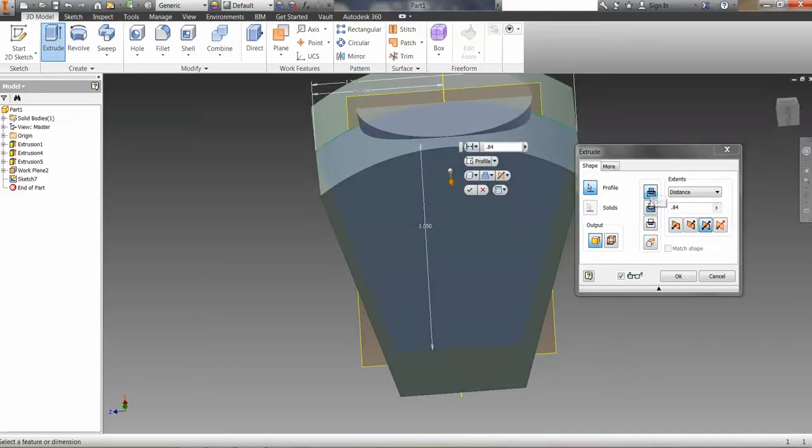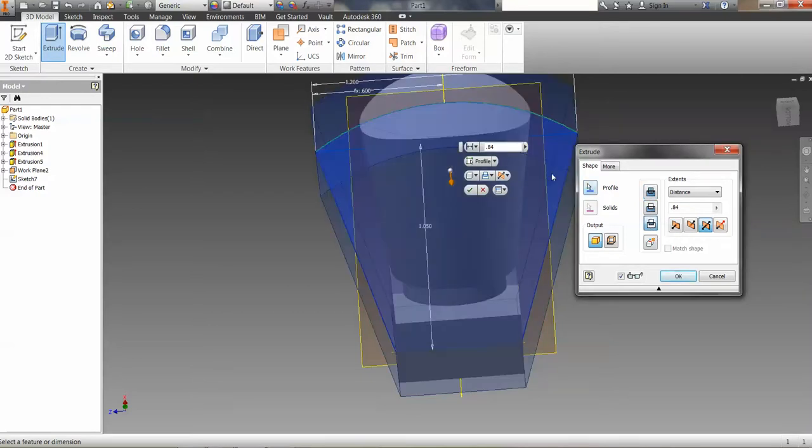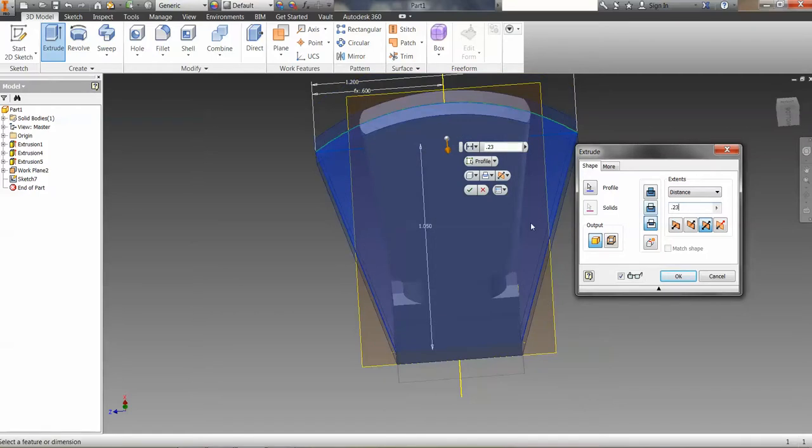We've done joins, we've done cuts. What we haven't done is an intersect. An intersect chooses where all of the previous extrusions and the current one meet. And it only chooses that. Everything else where things don't meet disappears. So we've got that. We don't have to worry about how much the extrusion is or anything like that. It's just going to do its amount. Now, if this number was too small, that could be a problem. It's going to cut it away, but we don't really need that.